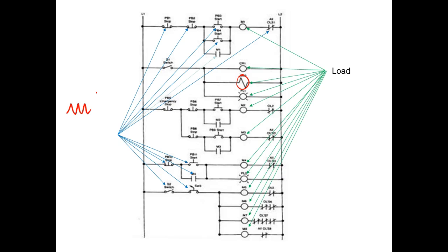So we can't put a motor starter inside a PLC because this is a power device. The PLCs are not power devices, they're control devices. Right? But we could put a regular control relay inside the ladder diagram for the PLC, and then you could control the motor. You understand what I just said?